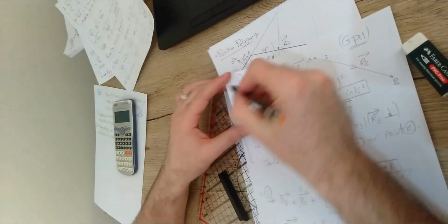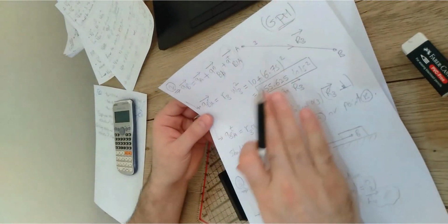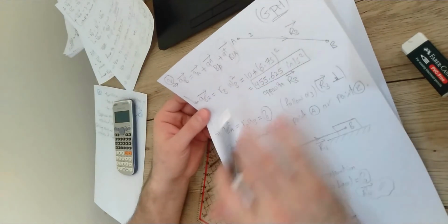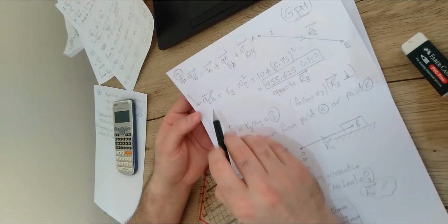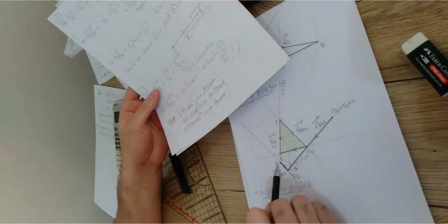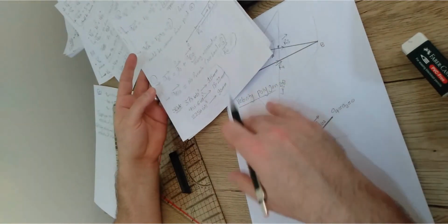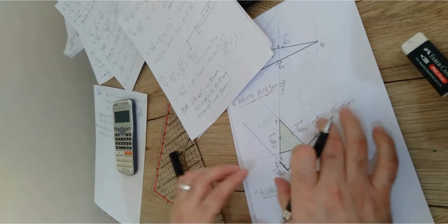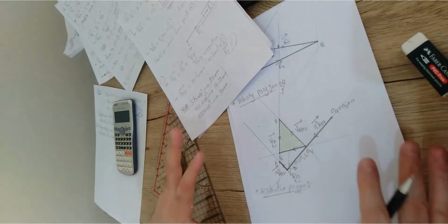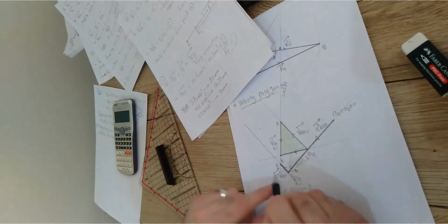We have done the first curve. Make sense? It is fully defined. Then we're going to move to the second equation. The second equation also has two components, one normal and one tangential. The normal is known, so I'm going to start by drawing the normal. But this normal should be drawn from either point A or point B, depending on which one is already given in the diagram. The point that we already have so far is point A. We don't have point B. Remember that this green thing belongs to the velocity diagram. I can move this one down, so I'll have some space, just to not confuse you. But anyway, let us continue.